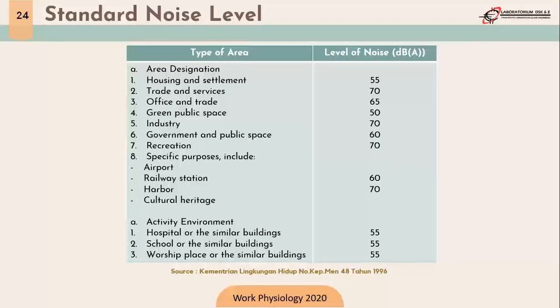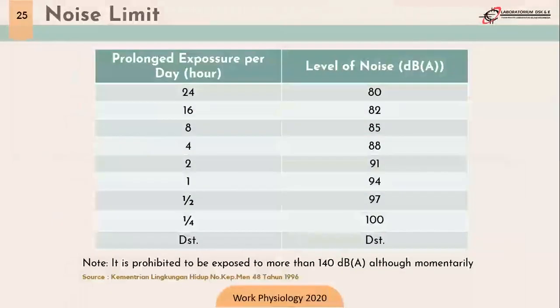And then, besides the type of area and environmental activities, noise limitation is determined by prolonged exposure per day in hours, like on this slide. Okay. You can take note it is prohibited to be exposed to more than 140 decibel, even momentarily.